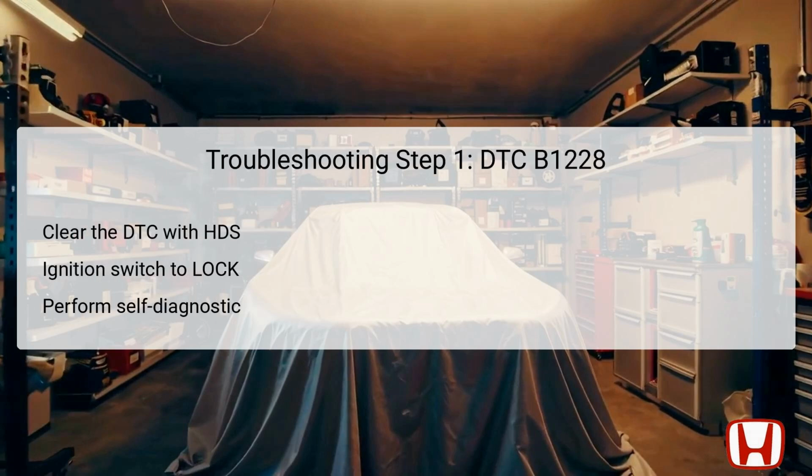The first step in troubleshooting DTC B1228 is to clear the diagnostic trouble code using the HDS, which stands for Honda Diagnostic System. Once the DTC is cleared, it's essential to turn the ignition switch to the lock position and subsequently back to the on position. This action resets the vehicle's systems and prepares it for the self-diagnostic test.